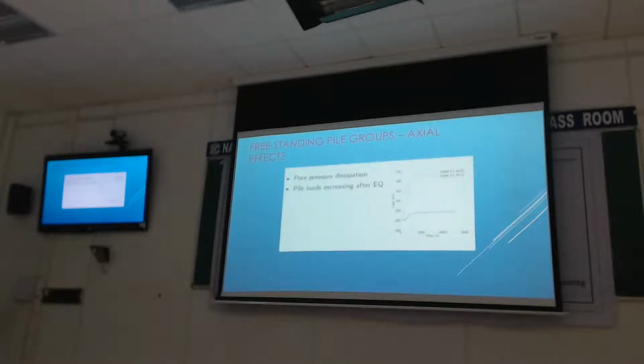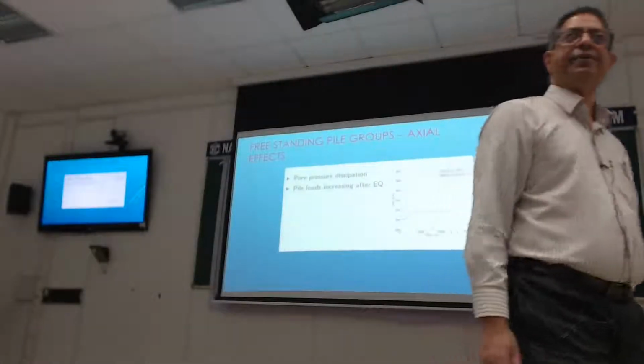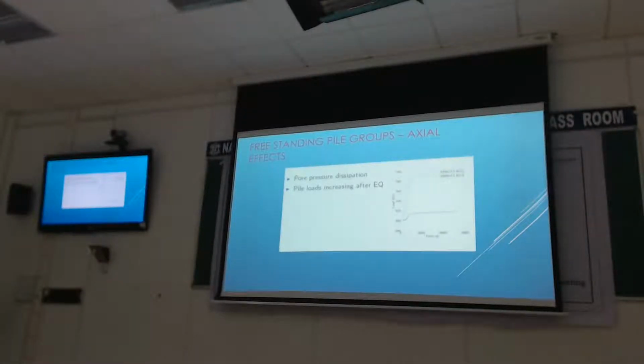The other thing we could look at is what was happening in the post-earthquake period. Because here, what's important is that during shaking you got big pore pressure buildup, but we want to see what's happening post-earthquake. Are they coming back or not? So as the pore pressure dissipates, we started looking at the load cells to see whether the pile loads are coming back or not. So you can see that these are picking up the loads in the post-earthquake period, which is good. That means that you are coming back to your pre-earthquake state reasonably comfortably.